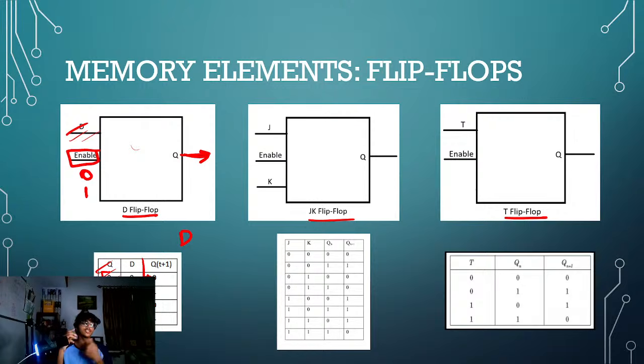When enable is 1, it's like a gate. When enable is 1, the gate is open. The D can affect Q in whatever way it can. When enable is 0, it doesn't matter what D is. Q just holds that memory. That way, you have a way of holding data. It's not temporary anymore. It's real data which is stored somewhere, using flip-flops. I hope that's clear. I hope whatever D flip-flop is, that's clear.